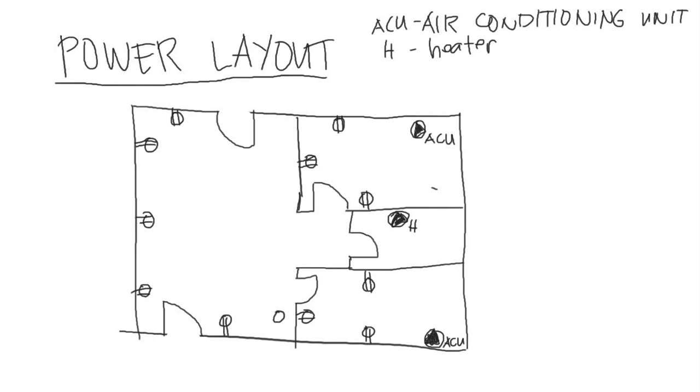So remember that according to the Philippine Electrical Code, the radius of use for a convenience outlet is 1.8 meters, meaning the distance from one outlet to the next outlet should be 3.6 meters.